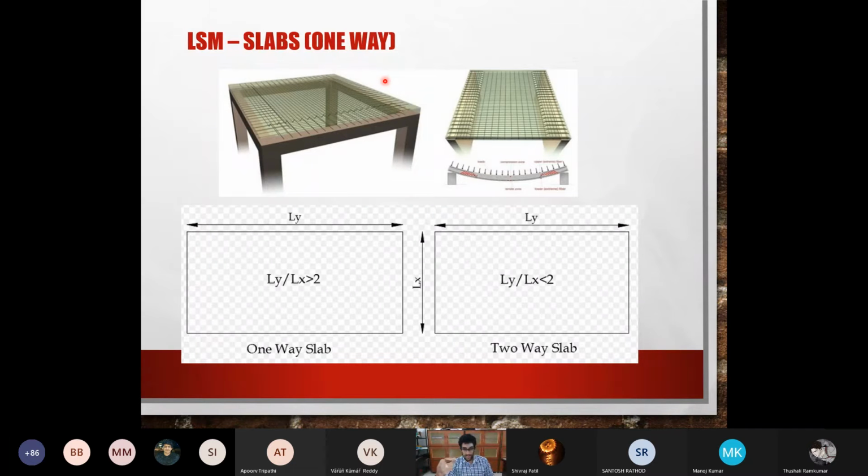Okay. So one of the problems when we solved for beam design, I told you that I had given you some floor area and told you there's a beam spaced this much apart, and then I gave you dead load and live load in terms of kilonewton per meter square. Do you remember the problem which I gave? Load was in kilonewton per meter square. Do you recollect that? Yes, sir. Okay, so that is the meaning of actually giving a load in a kilonewton per meter square, meaning it is an area load or it's acting on an area. What is that area? It's the area of the slab or the slab panel which is given to you.